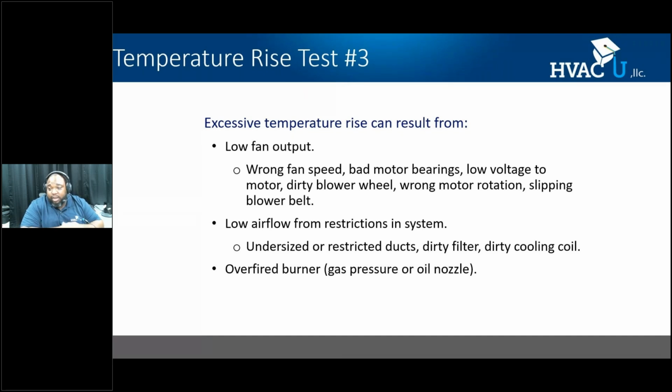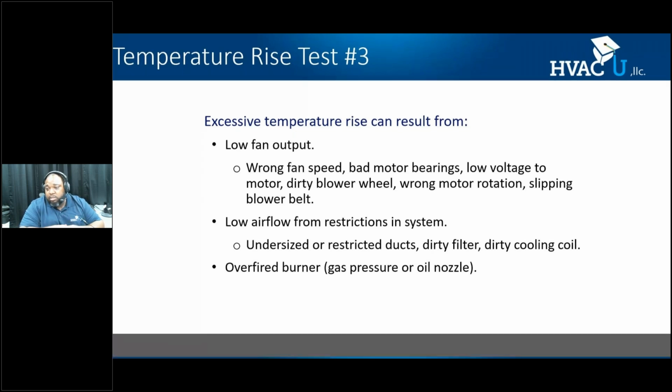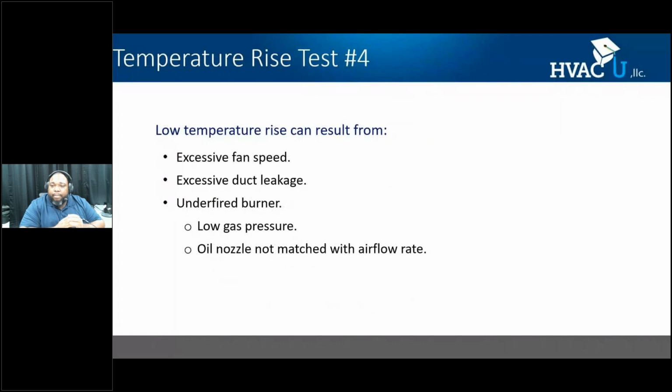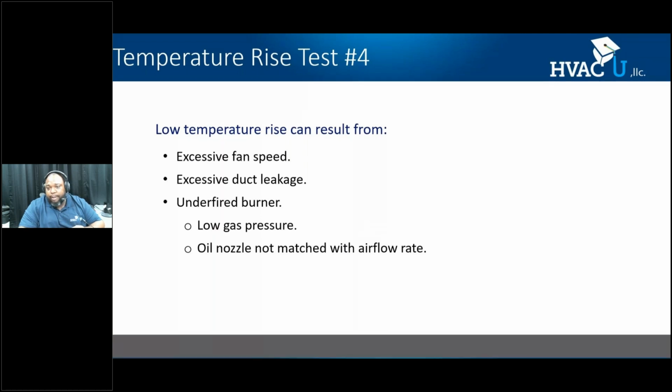and my temperature rise. You can also have a high temperature rise from a burner being overfired, such as a gas pressure issue or maybe the improper oil nozzle size. All right. Low temperature rise can come from excessive fan speed, excessive duct leakage, or an underfired burner, such as low gas pressure or improper fuel oil nozzle.